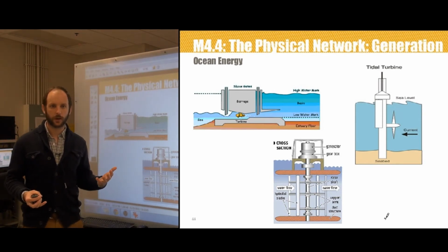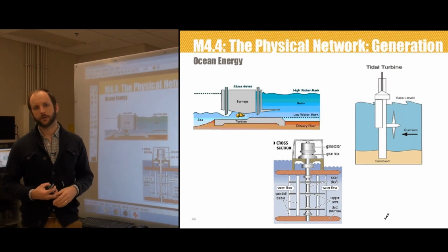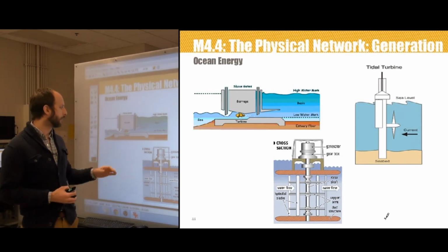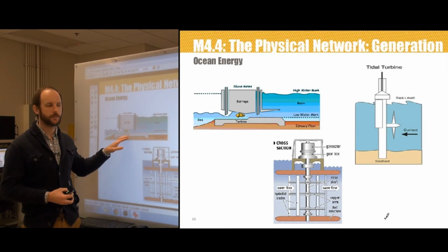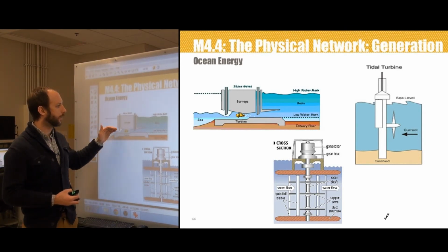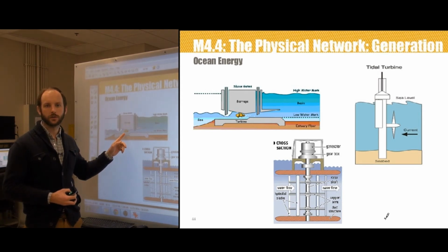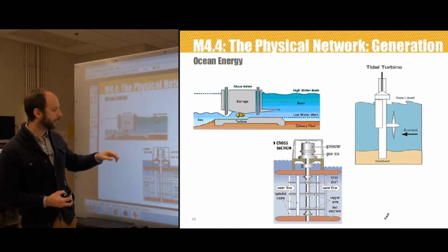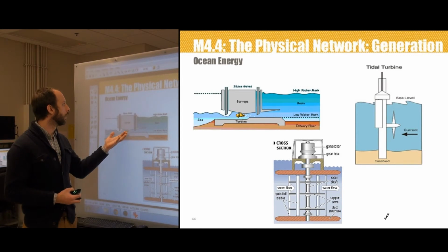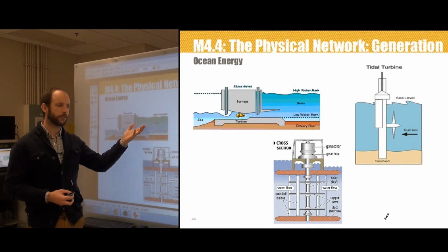So first, let's talk about tidal. Tidal power can be converted into electricity in 3 ways. The first is that we've got a barrage or a dam, and what happens is seawater gets forced through a submersed turbine. So we somehow channel the water from the tidal flow.